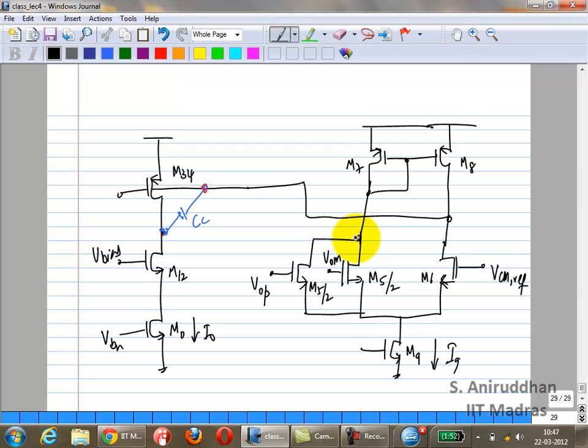So if you look at the resistive detector, we are discussing everything with respect to a single stage op amp. Okay. What is the output swing? We have not discussed that at all. Output swing can be quite large. The resistive detector gives you VOP plus VOM by 2 irrespective of how large the swing is. In this particular case, this detector is linear only for very small swings.